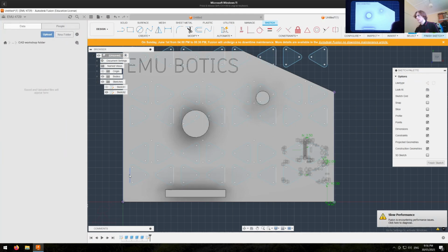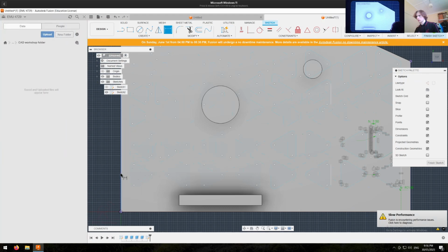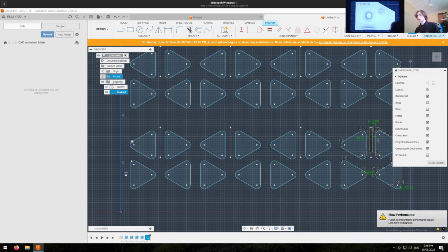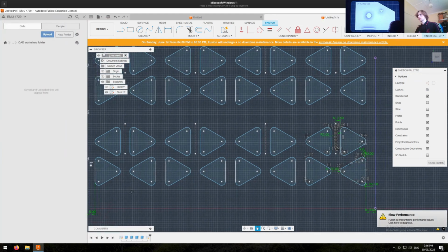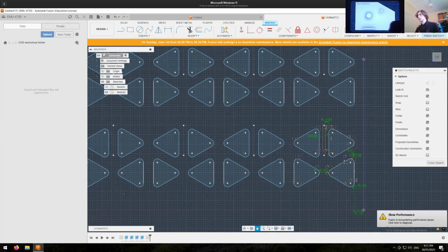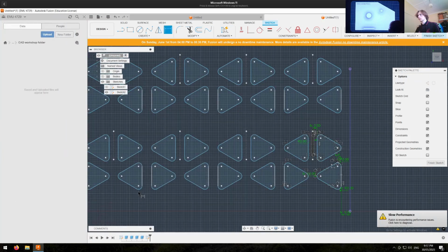And then I believe I actually can get away with dimensioning this outer line. So I'm going to press escape. And then let's hide this body. And I'm going to select this and then D, enter. It's going to think really hard. Yep, you're happy with it? Cool. And then everything else seems to roughly line up.